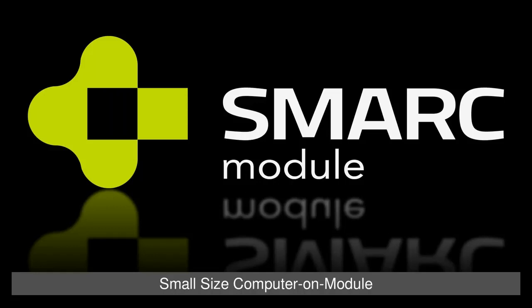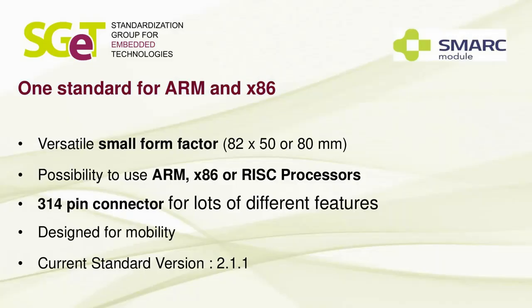Our first standard that we developed like 10 years ago was the SMART module standard. It's a small size computer on module. And what makes this standard stand out is it's one standard for ARM and x86. It's a quite small form factor, 82 by 50 or 82 by 80 millimeters in size, and you can use ARM, x86, or even RISC processors with it. It comes with a 314 pin connector that offers lots of different features.